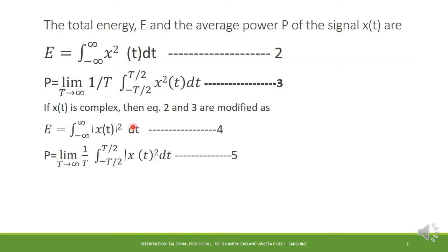First, you have to take R. R is nothing but the resistance that is excited by the voltage v of t. When excited by the voltage, it is going to give you the current, that is i of t. Because R is equal to 1, v of t is equal to i of t. That means current is equal to voltage, and that we have taken as x of t.